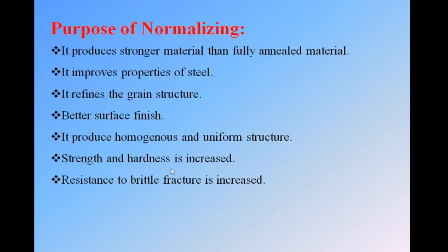Next, strength and hardness is increased. Strength and hardness is increased because, as it is a normalizing process, it has a high cooling rate as compared to annealing. It will have the high hardness. As it has high hardness, it will have high strength.